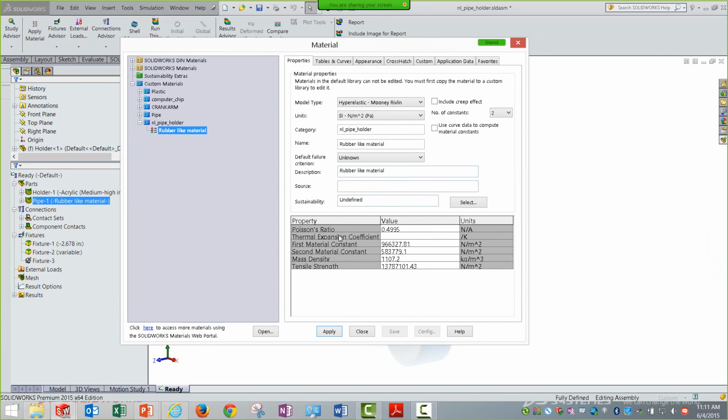Unfortunately, there are fewer standard rubber materials available publicly. Hence, most of them are customized. Other way around, most of the companies have the stress strain curves as per the requirements of rubber components. So those can be input directly in the software, and the software calculates something called constants as per the theory used. One of the theories is hyperelastic Mooney-Rivlin, or if it is foam, we have the Ogden model. We can also have hyperelastic Blatz-Ko.